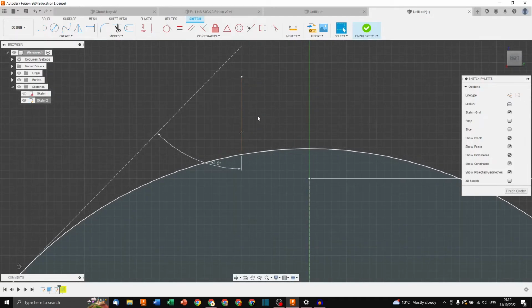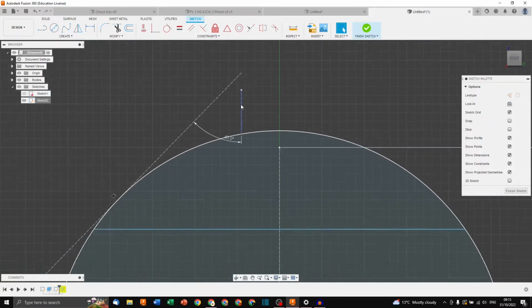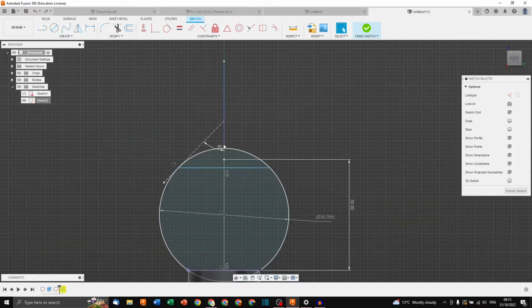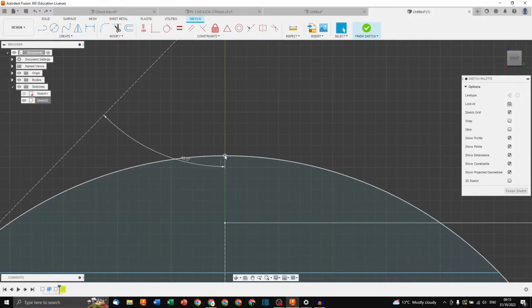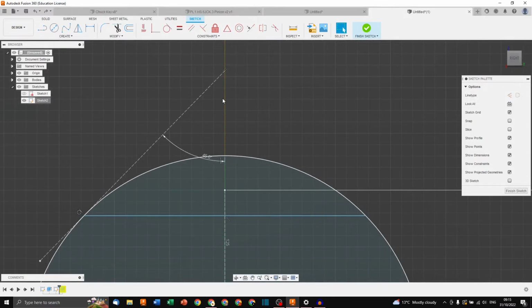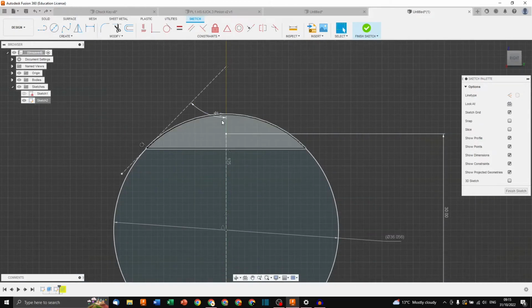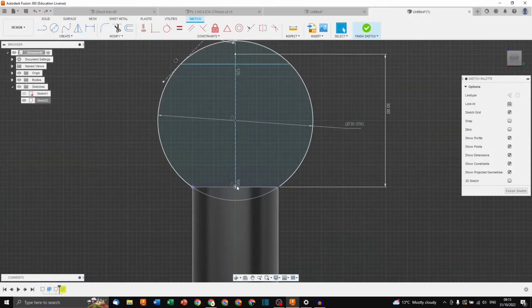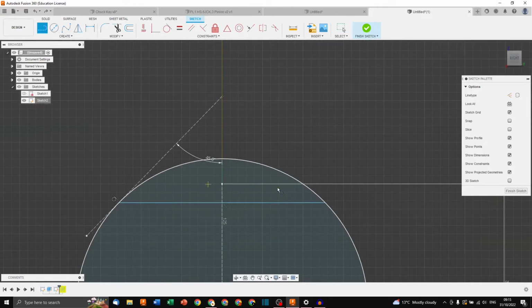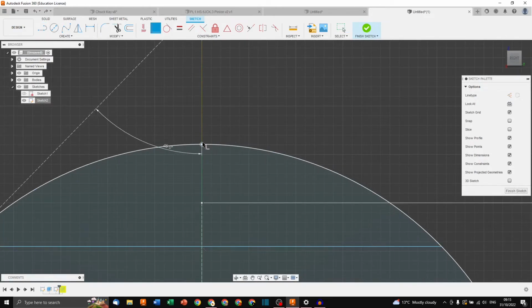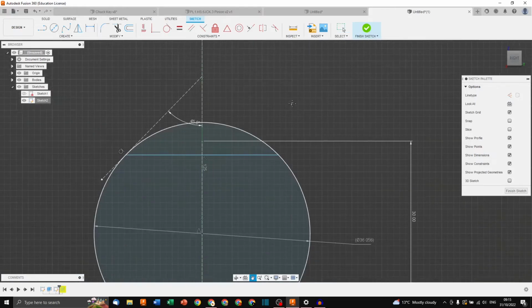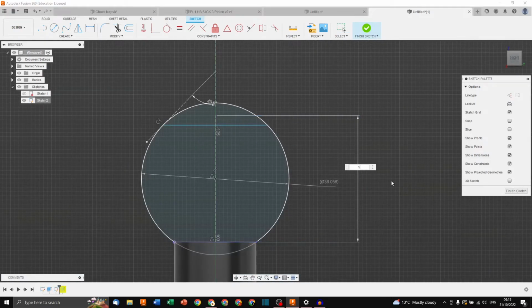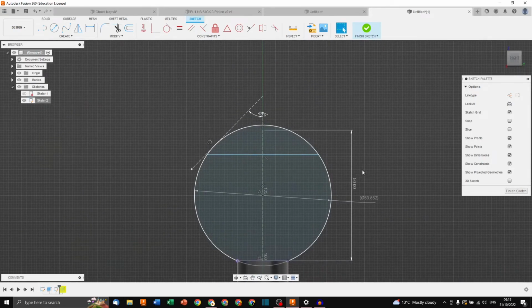So it didn't work, because I didn't constrain this line enough. It was fine before, but it wasn't constrained enough, because I told this line, look, you need to start from a point in this circle, and you need to be vertical. I didn't tell it where it had to start from based on the origin. So if I say that it needs to coincide this line and this point, now it became white, this drawing line. It was orange, so it was not fully constrained. I made a mistake. If I switch it to 50, everything works perfectly well.